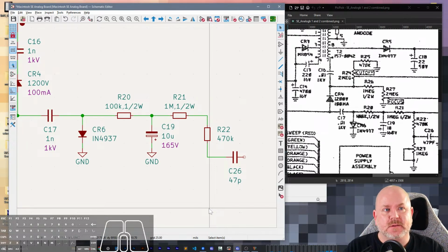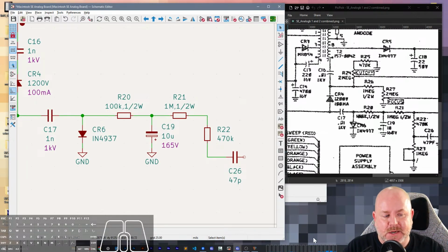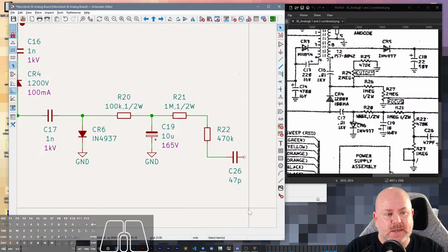It does help with lead-free solder, but it's not nearly as impactful. The downside is that if you mix lead and bismuth, you've changed the melting point. So if you have something like a regulator or a transistor that gets over 140 degrees C, you may not want to put bismuth near it, or you have to do a really good job of cleaning it.